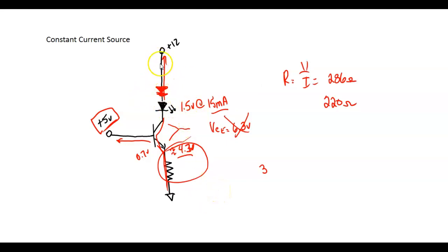But yeah, I did. And you can see 1.5 volts a piece. I'm losing 5 right there. We could probably run about 4 or 5 LEDs. So it's constant current. If I've got a NiCad battery, I can just put my battery in series right there, and it would charge at 15 milliamps.